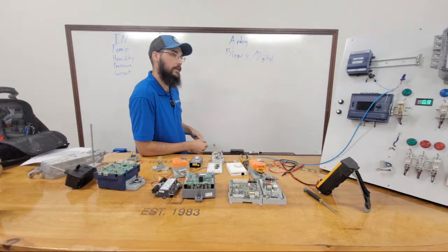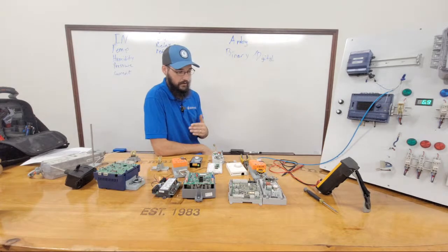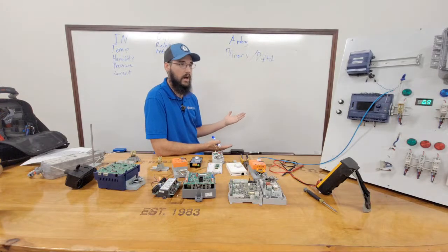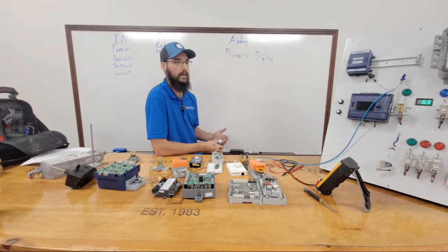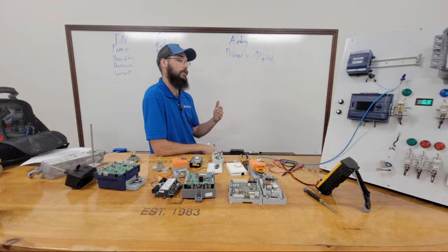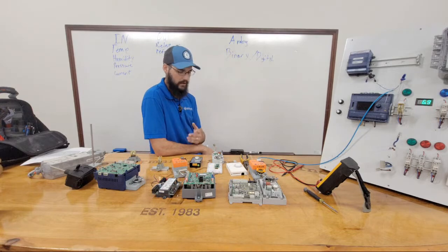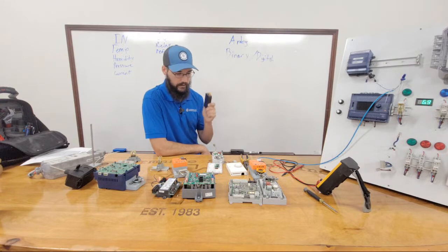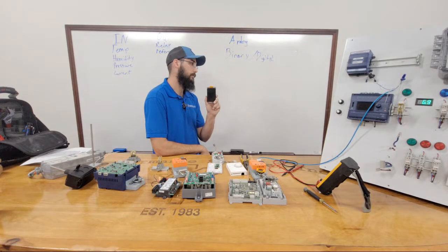I guess that does kind of bring up an interesting point. So I think most everybody is pretty familiar with the analog signals are typically a varied voltage, most common 0 to 10 volt DC, I think is the vast majority of what you're going to see out there. At the same time, it could also be a milliamp signal, so a 4 to 20 milliamp. And actually, I meant to grab a relay and a resistor, realizing I forgot to.